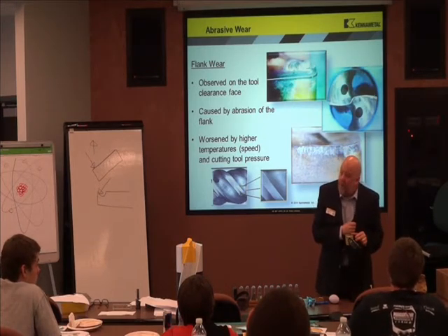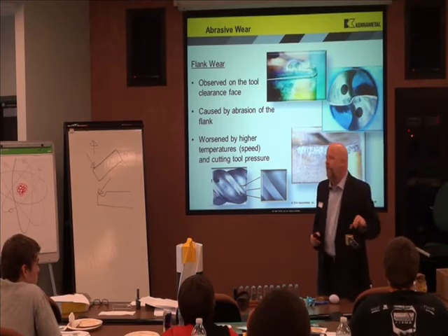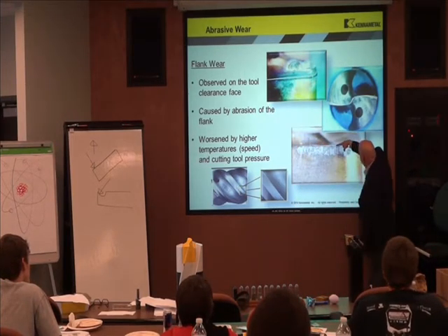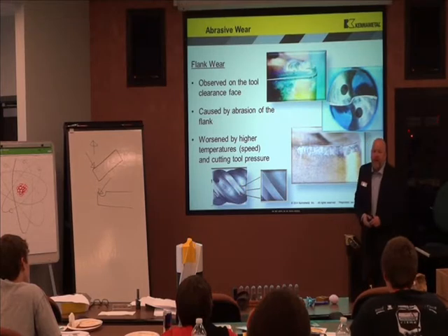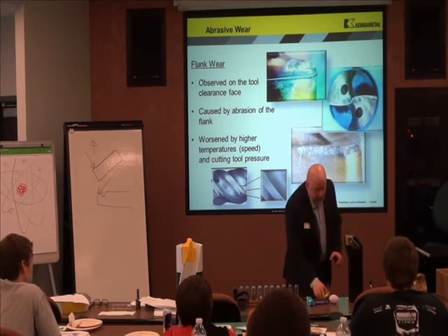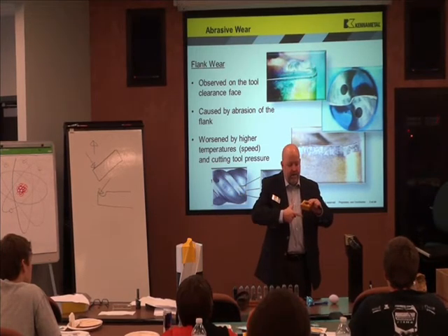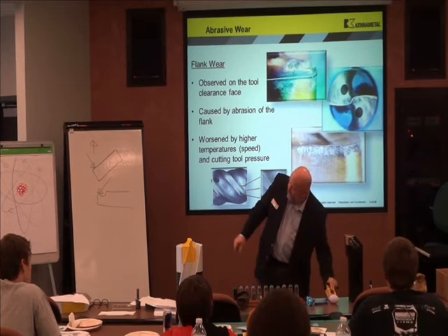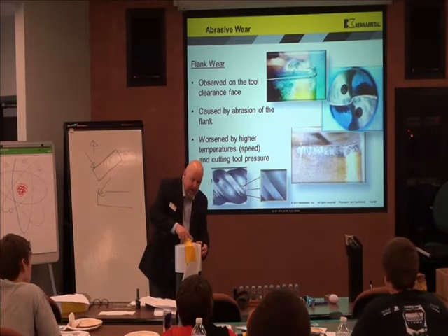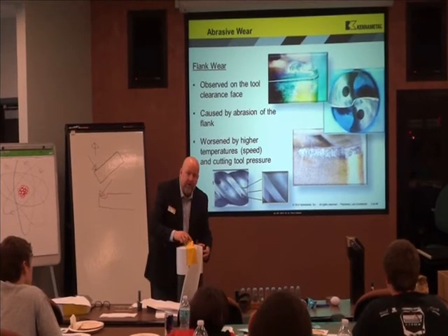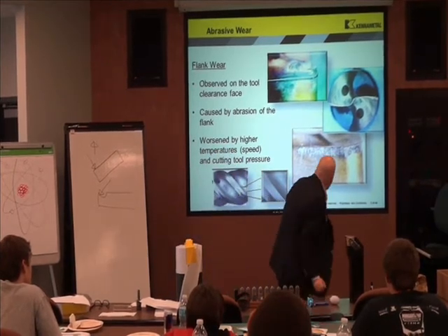Actually, if you're looking at real wear, which is silver, silver shows up better on black than it does on gold. It is a silver line that starts on the cutting edge and goes down the flank. If I look at the flank on an insert, if this is my rake face, it's the adjacent surface. If it's my tool, drill, here's my cutting edge, it would be on the clearance face. That's where you see the silver line.